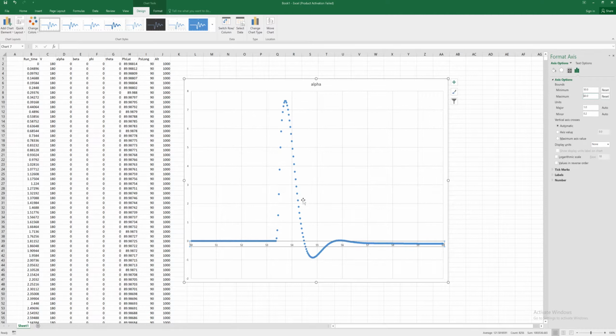And it's fairly high frequency, right? So if we measure the time between peaks, here's roughly a peak and here's roughly a peak, from about 53 and a half to almost 56. So we're talking about a 2 second period there, right? And 99% damping time, probably 2.5 seconds or something by the time that's completely damped out. So again, this is the short period mode. This is what we experience when we hit a gust or turbulence.